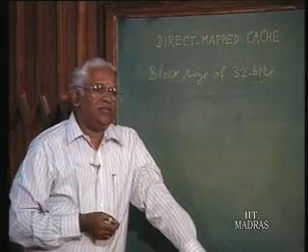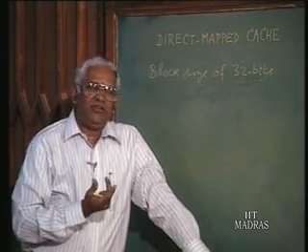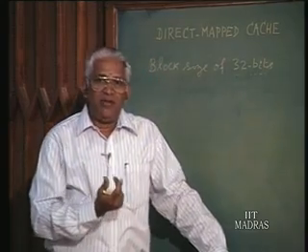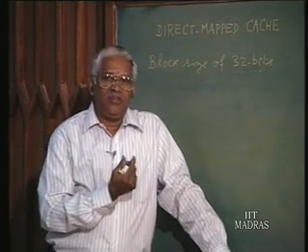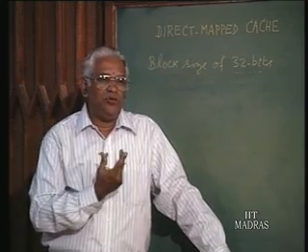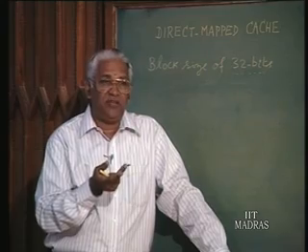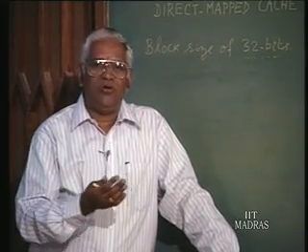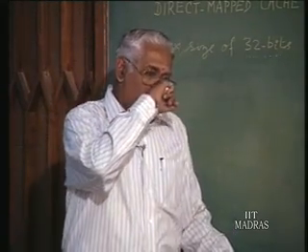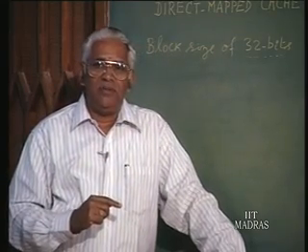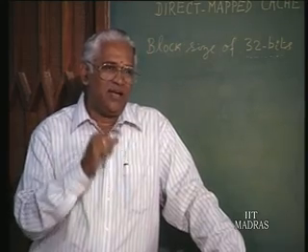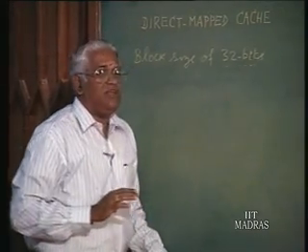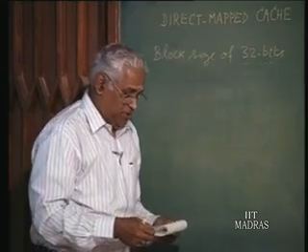But then we also said earlier that generally the memory is organized byte oriented, that is byte organized memory. That is, any time we may be interested in getting at a byte of data. Now, when we have 2 bytes, generally it is called a word, that is 2 bytes is 16 bits, right. When we have 32 bits, then it is called a long word, and then 64 bits very long word, and so on and so forth. These usages keep varying. Though we may have word, long word, very long word, generally we are also interested in accessing at the byte level. So, what exactly is the data that will be subsequently used by the processor depends on the processor size.